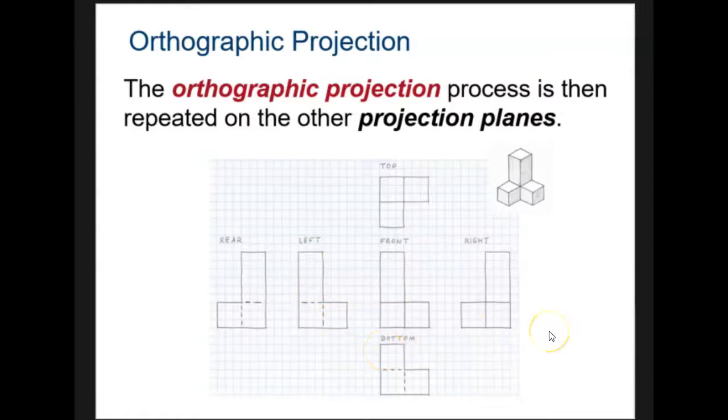So there are 6 principal planes as indicated here. In most cases, 3 or fewer orthographic projections are needed in a multi-view in order to fully describe an object. Most of our multi-view drawings will only have 3 views: the front, top, and right side.